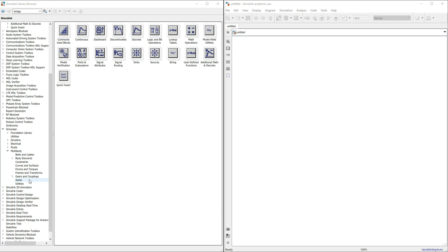Right, so from multibody, we need to establish the ground. Don't forget, we need to say where our starting point will be in any type of CAD system, simulation system, any computational fluid dynamics problems. You always need to define what your reference geometry will be, where you're going to come from. So what we do with this is we define a world, or a ground, or a start plate. In essence, this would be our 0, 0, 0 marker of what we would see in any CAD system. So I'm going to click Utilities,